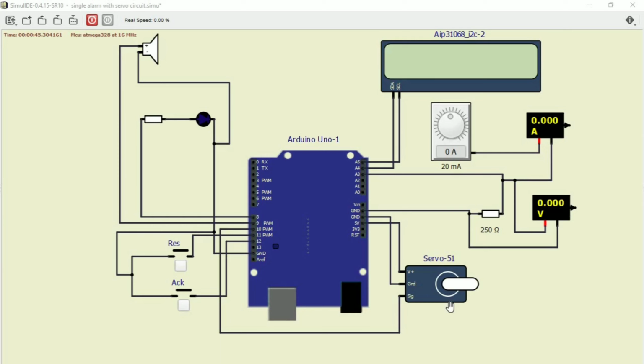And again, about the servo motor or the IP transducer valve, this is responsible for maintaining the water below the high level alarm or above the low level alarm. This will fully open at negative 10 or less, and will be fully closed at positive 10 or more.